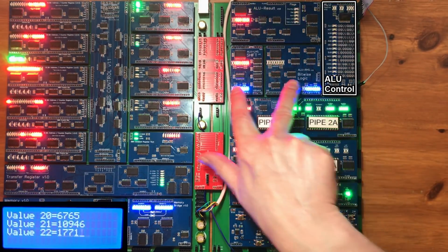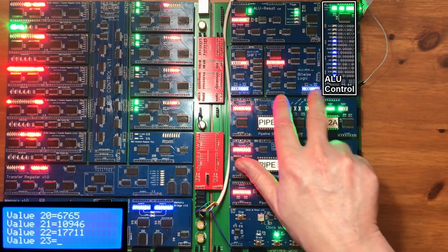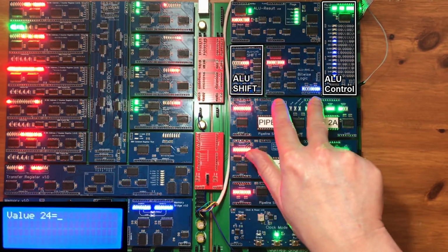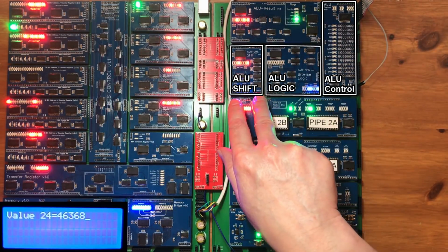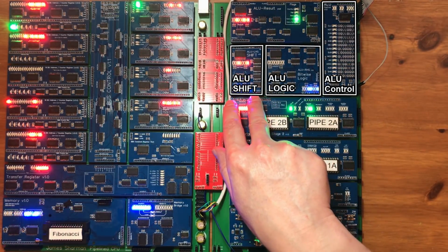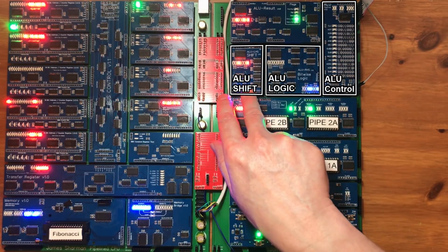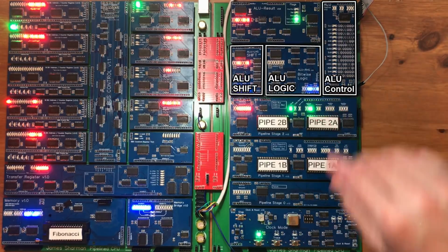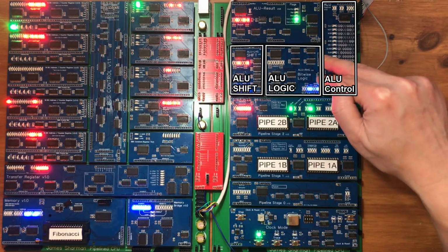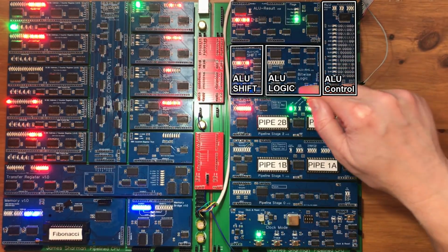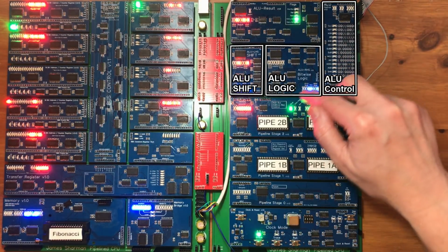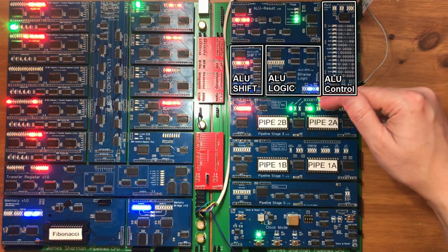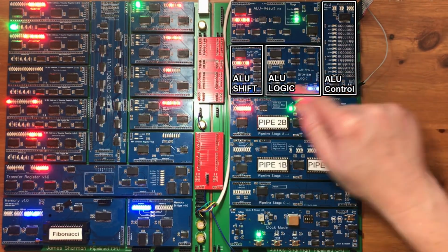So then you've got the two halves of the first stage of the ALU. You've got the left side and the right side, which are shifting and bitwise logic. The shift unit will output a value unchanged, shifted up by 1 bit, shifted down by 1 bit, or it can also output a 0. The logic side has both the left and right inputs into it, and it can perform a logical operation between those. So it can do a bitwise manipulation of its right-hand input or combine it with the left.